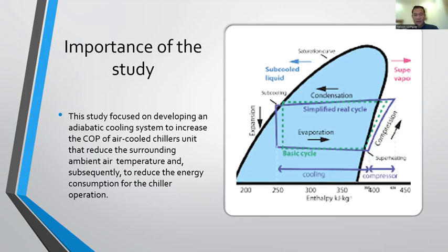So this study focuses on developing an adiabatic cooling system to increase the coefficient of performance of air-cooled chiller units that reduces the surrounding ambient air temperature and subsequently reduces the energy consumption for the chiller operation.